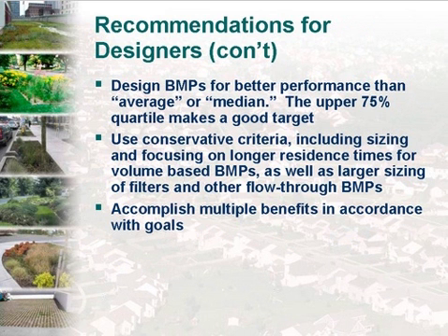Right, and the whole caveat behind pollutant efficiencies, which is how we started off this discussion, is that the center database is largely based on percent removal, and these measures really aren't an accurate reflection of BMP performance. And so what the center has advocated is that if you are using the median value, you're going to get mediocre performance out of your BMP. And if you're going to make this substantial cost investment, do you really want mediocre performance? I would say not. You really want to get the most bang out of your buck for that.